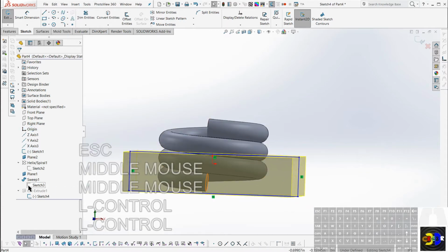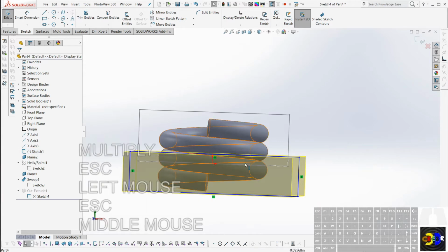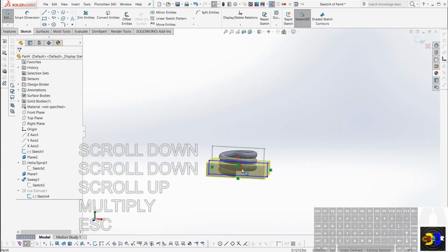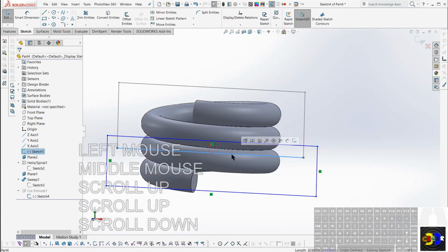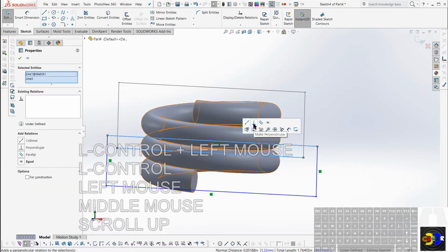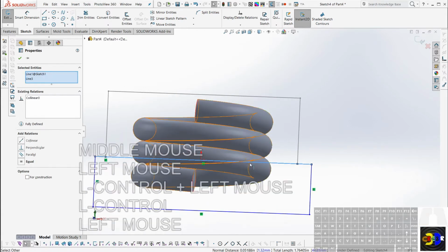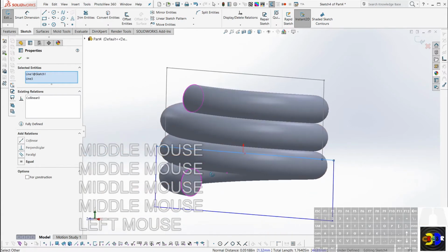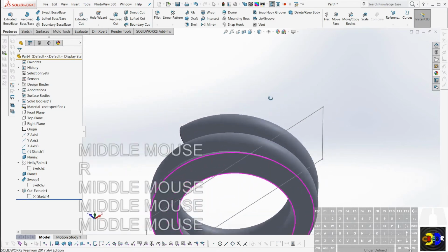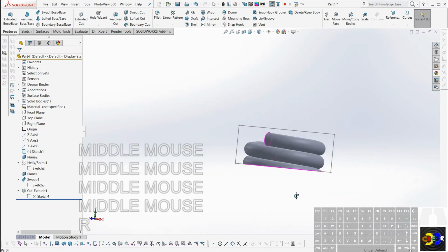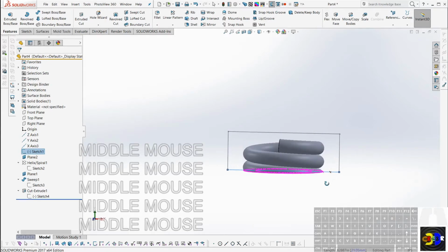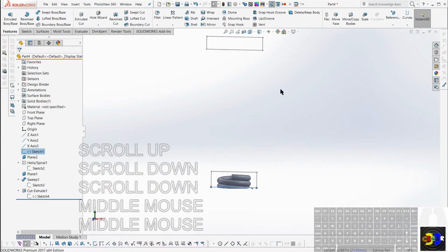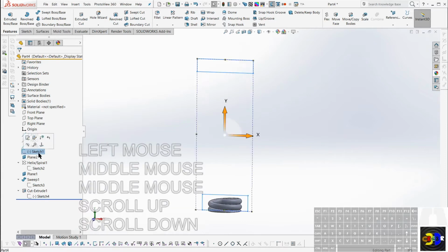or you know what? Let's just turn on the sketches because I have this sketch as my sort of skeleton sketch, and so I'll select that edge and I'll select this edge and I'll make them collinear. And so now my subtract cuts off the end of the spring right at this plane here, at this line of my defining initial sketch.